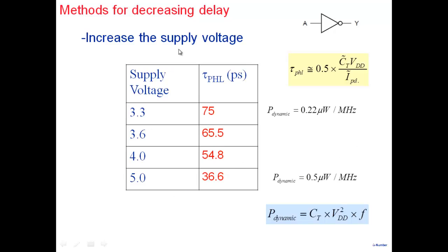The other one, a harder way of changing the delay, is by changing the size of the inverter. And we said that if you look at an expression for delay, there's an intrinsic part and there's an extrinsic part. The intrinsic part, to the first order approximation, doesn't change that much with the size here, but the extrinsic part, the inverter has to drive a load capacitance here, and this factor A is directly proportional to the size. So if there is a heavy capacitance or whatever attached to the inverter, and that's contributing a lot to the overall delay, well, you can increase the size of the inverter.